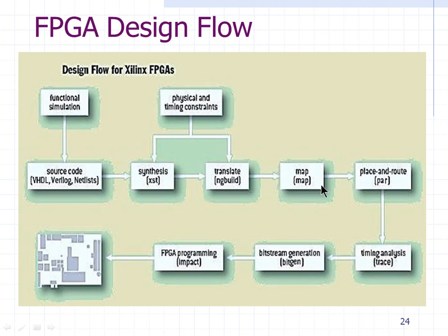But typically synthesis and everything onwards is part of back-end activity, and this is part of front-end activity, where you will write Verilog code for your design specification, test your Verilog code, simulate it, generate timing diagrams and other reports, and check whether everything is working correctly as per the design specification or not. If not, you have to fix it. These steps take around 60% of the time, and the other steps take less time because they are mostly automated using specialized software, EDA tools, as we have seen.